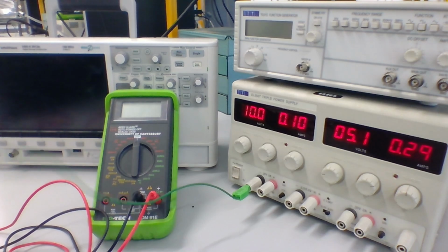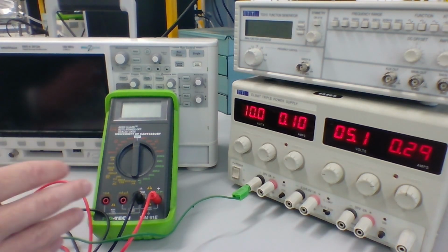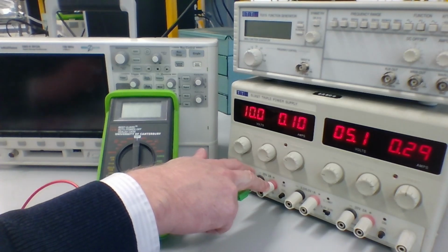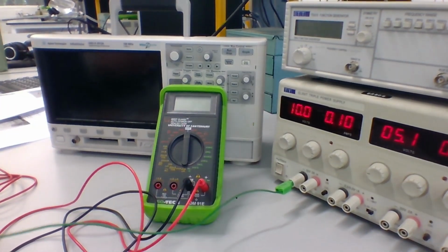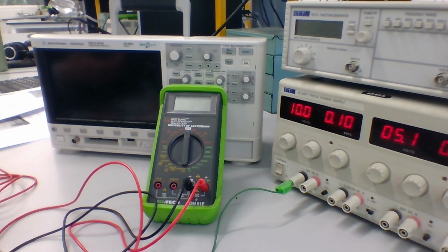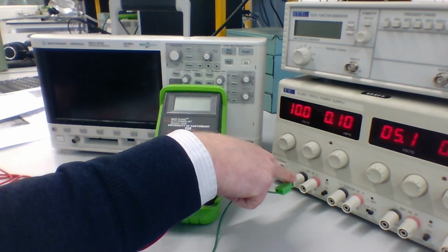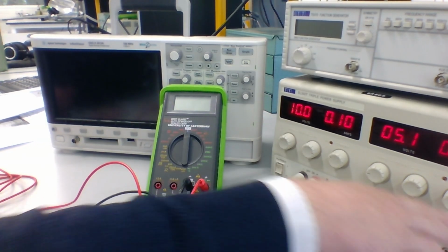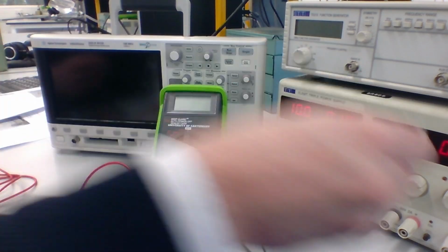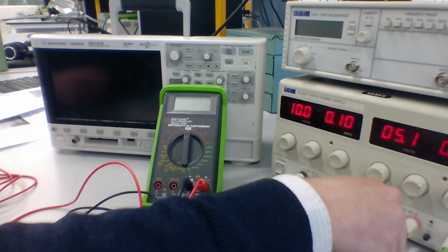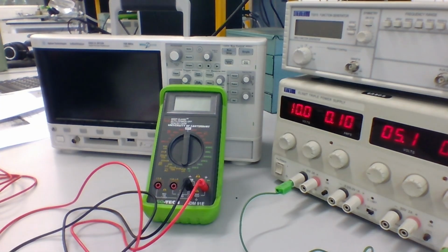For this lab, this isn't strictly necessary. With a single power supply, using the positive terminal referenced to the negative is fine. It won't make a difference. But this is a good habit to get into of earthing your negative reference. Otherwise, if you're using multiple power supplies and you don't have a common reference, they will have different voltages between each other. So by connecting the negative terminal to earth, we ensure that all of these are referenced to earth. So it's a voltage with respect to earth. So it's a good habit to get into, as again, using a single power supply, it doesn't actually matter. It won't make a difference for this lab.